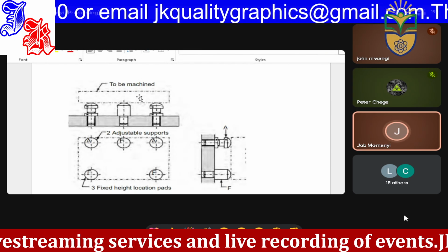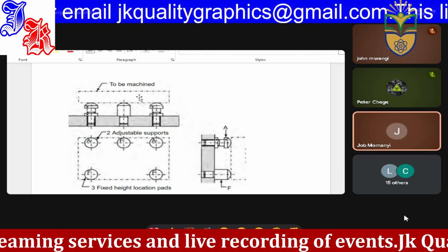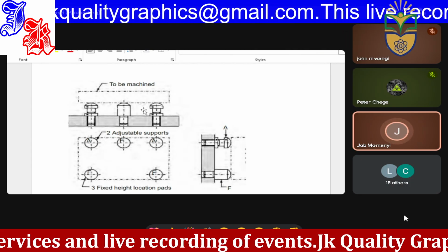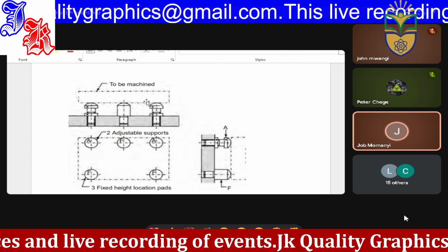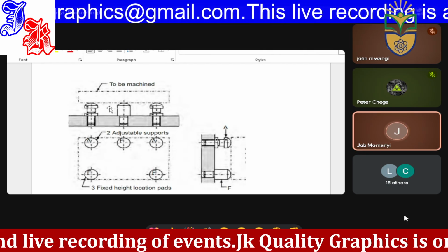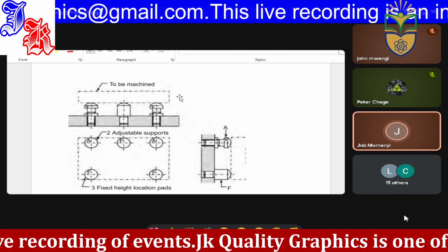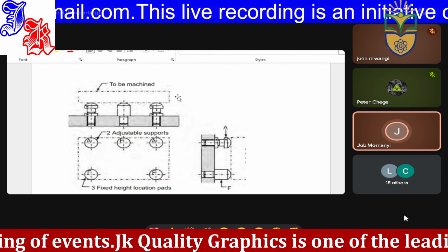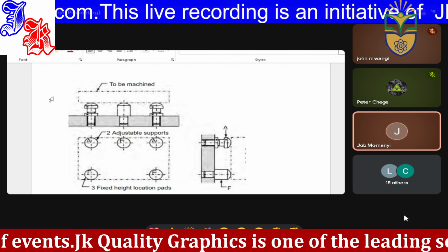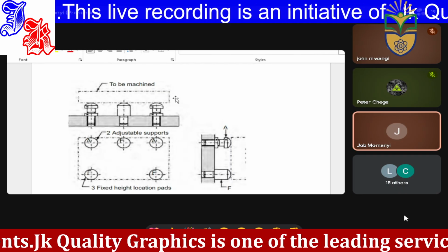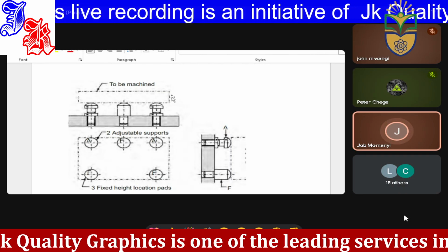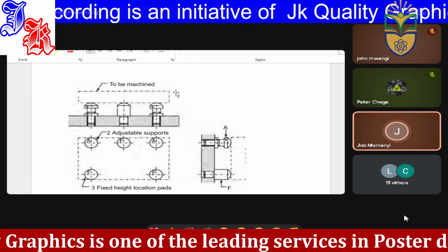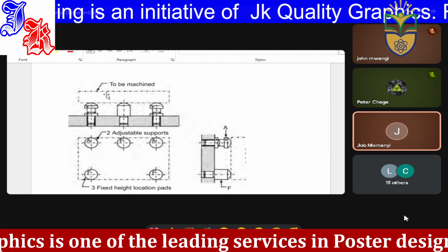And because the milling cutter has a downward applied force, the lower pins will support the workpiece. So we don't have locating pins from the right, because the cutting tool is moving from the right to the left. There's no need of having support from the right since the force is directed towards the left.